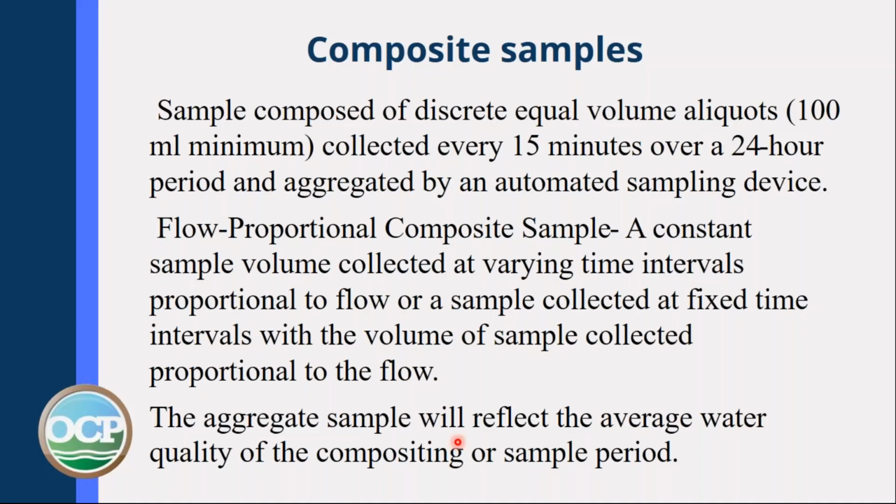And then you have time aggregated samples, which are basically just collecting a certain volume, say every 15 minutes. So the sample that you collect when you test it will reflect the average quality of that water over the sampling period.